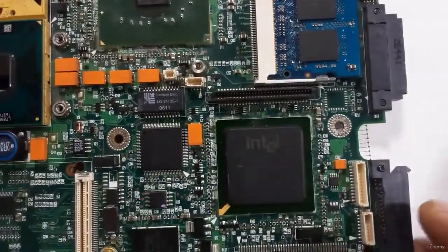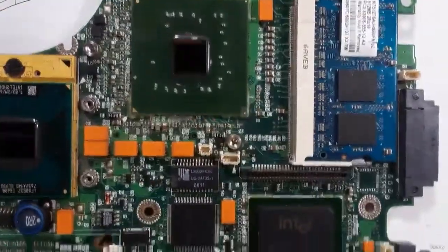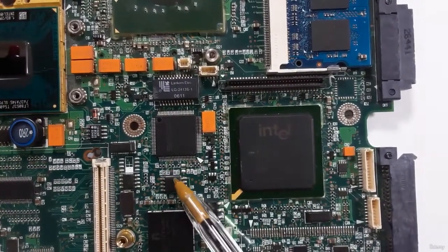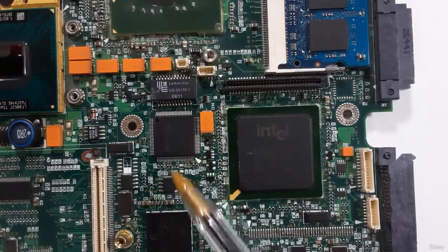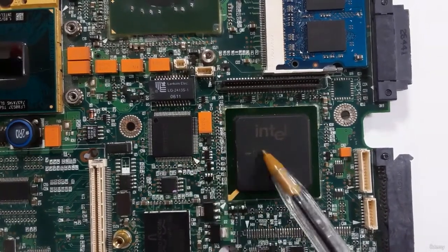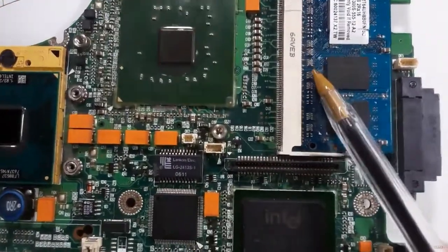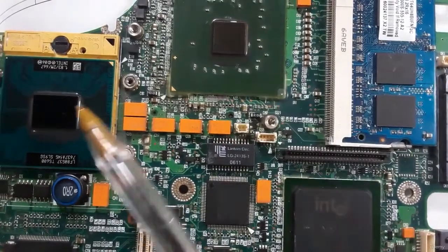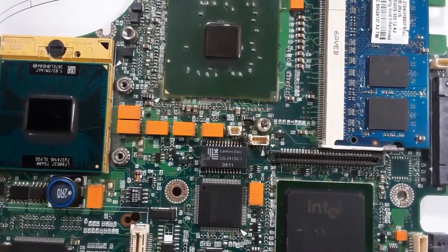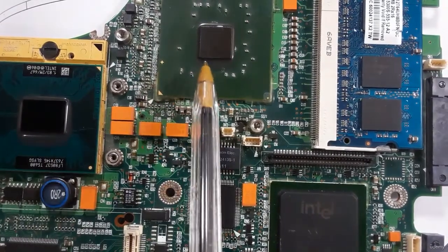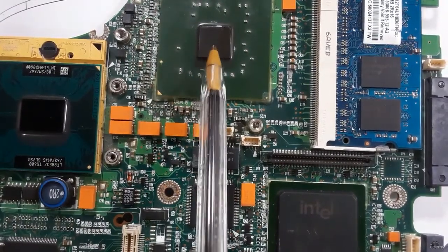So in the motherboard, as you can see, this is the ICH. We always find the ICH near the BIOS and near the Super I/O. So this is the BIOS, the Super Input Output, or Super I/O. Here we have the ICH. Here we have the RAMs. Here we have the GMCH, and here we have the processor. Always next to the processor we have the GMCH or the Northbridge.